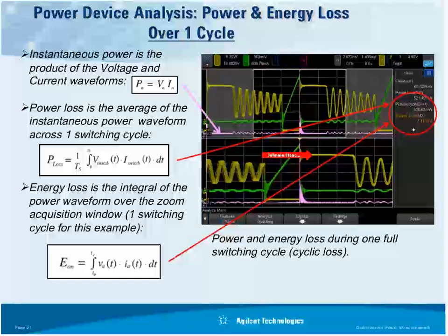If you want to measure this voltage accurately, the problem with the oscilloscope is you cannot measure this voltage accurately at the same time. We just don't have enough resolution and accuracy. Now you may say, well, why not just get a scope with more bits of resolution? Well, that would improve the resolution of the measurement, but it would not improve the accuracy.